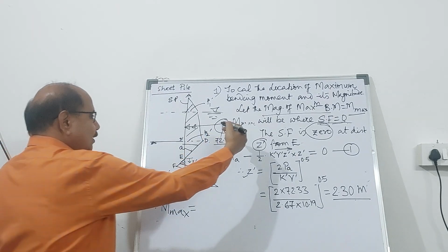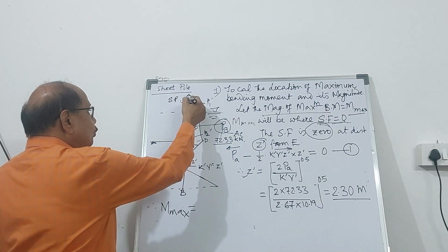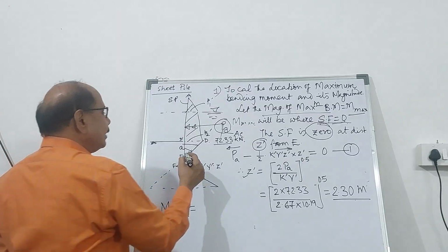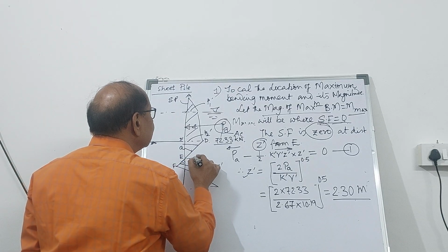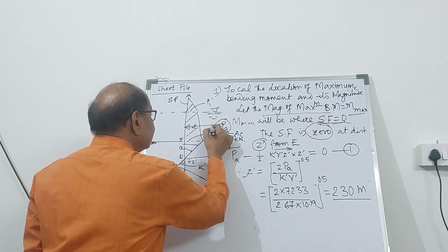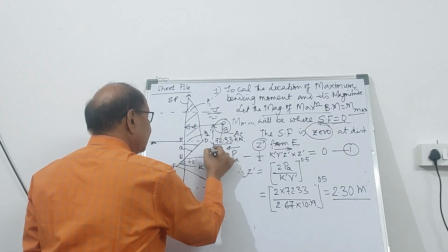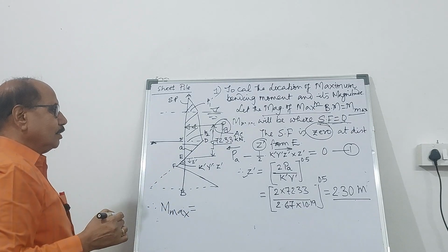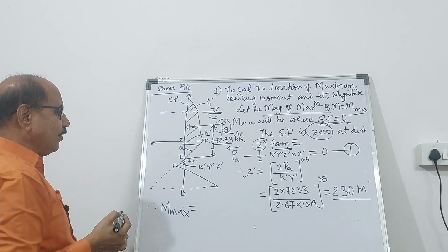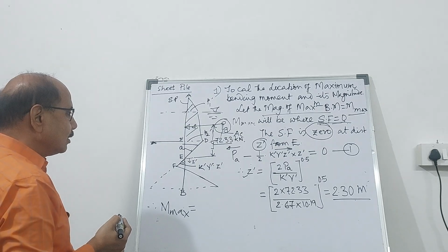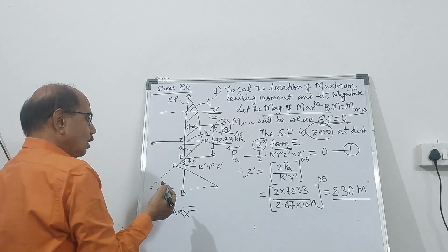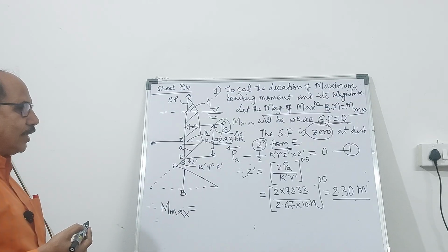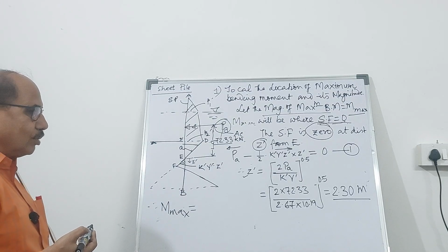So now the force is PA, from A to E it is going to be the active pressure, and from E there is the Y bar, that is the location of PA from E is Y bar, is known to you. And in the last video, we have been able to calculate the value of Y bar also.